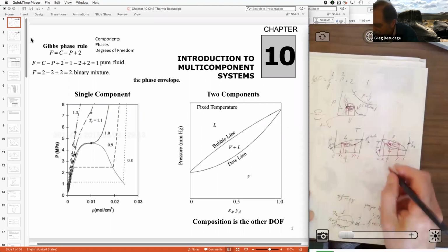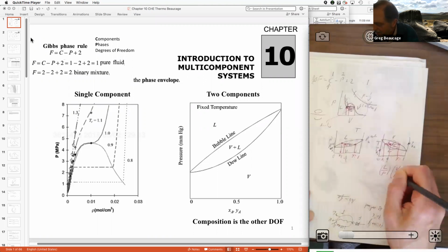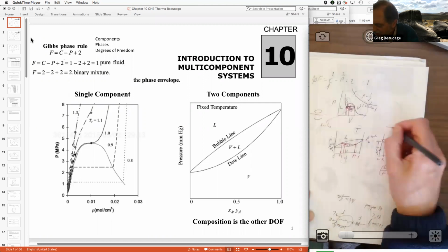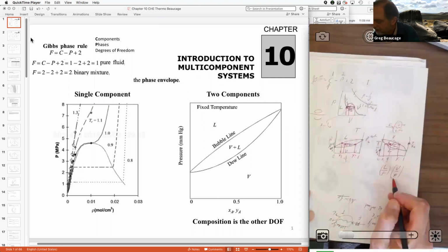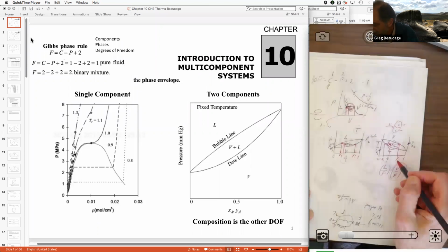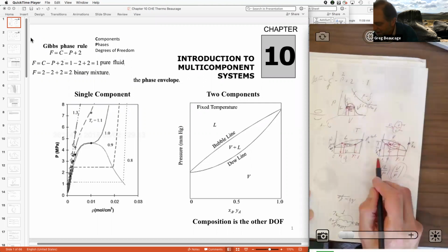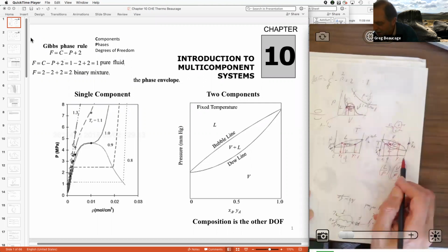Right, so we're going to talk about liquid by feed or vapor by feed. For a flash tank, you come in, it's going to flash, it's going to make a liquid and a vapor. So you have the feed, so you're going to have this kind of V by F number, the parameter you want to get out of the flash. And the composition is going to be given, like the Y compositions are here, the X compositions are here. So this is set up for binary. In other words, you have ethanol and methanol mixed. So you're going to have a fraction of methanol, and then 1 minus that will give you the fraction of ethanol. You can also have multiple components.